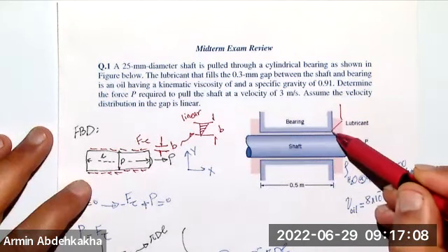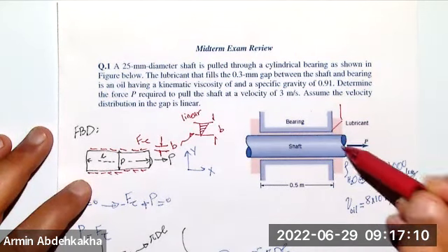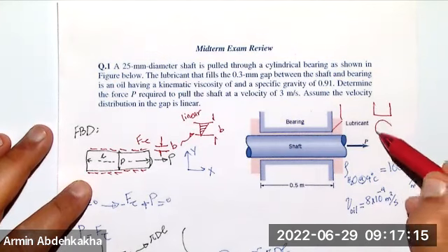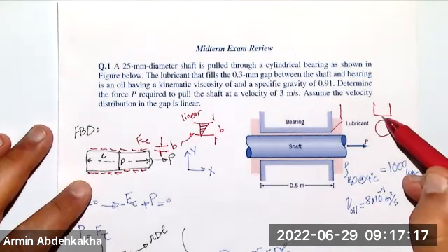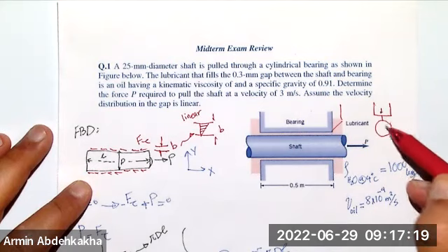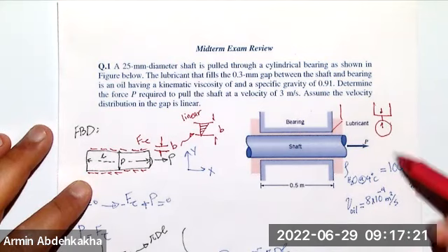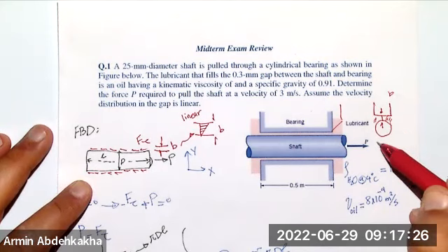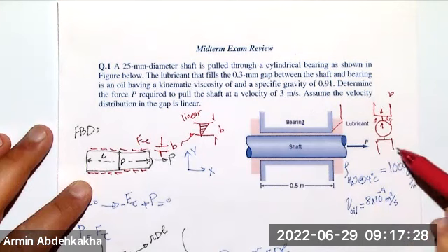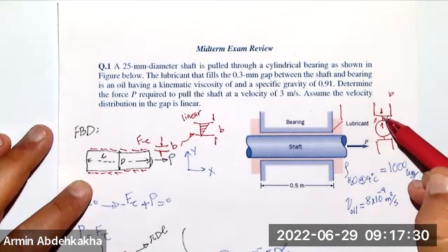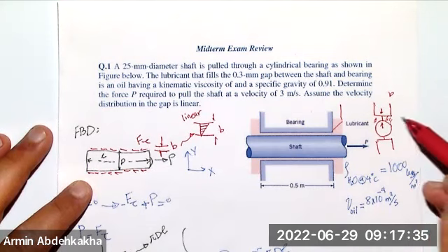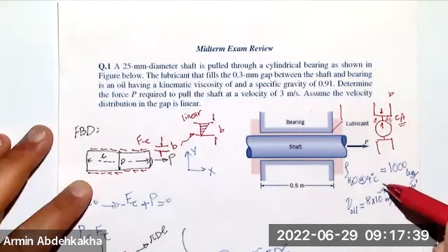Then only in one line, because that's a circular shape. So in side view, you will have this, right? Then you only have one line where the distance is going to be B. The rest of that is not. And also in bottom, you will have the same, only one side. So it doesn't make sense to find tau here. Why? Because you have to find tau times area, and area of the line is 0.